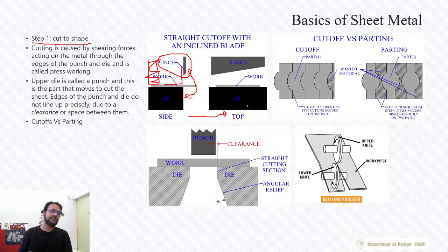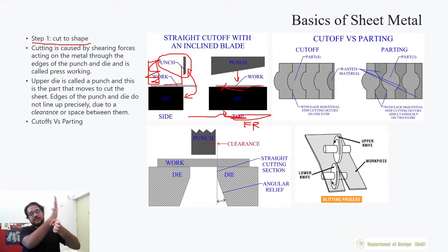This same thing is shown from the top this way. Actually, this is not the top, this is the front. From the front it looks like this, the punch is like this. When the punch comes down, you can imagine the gap between these two materials traveling from one end to the other, and this behaves the same way as scissors. So this is the shearing operation.